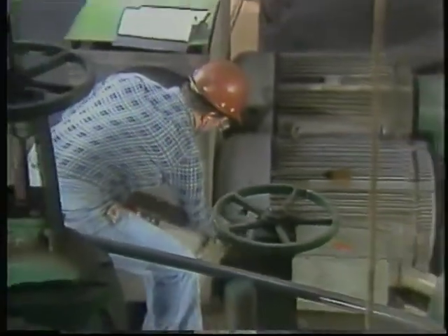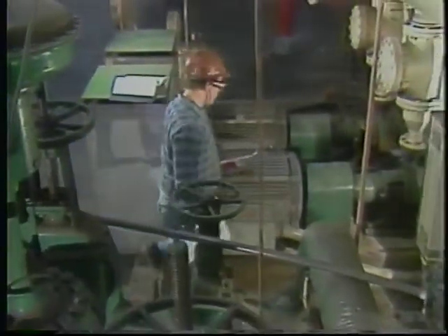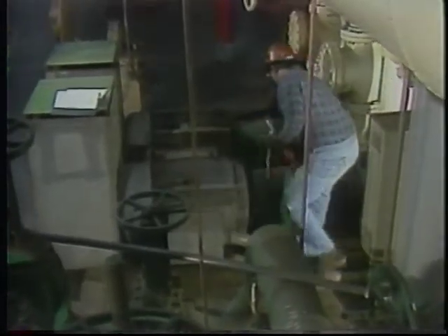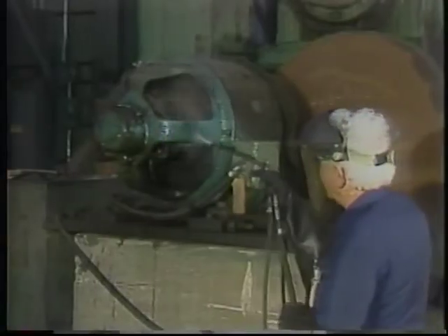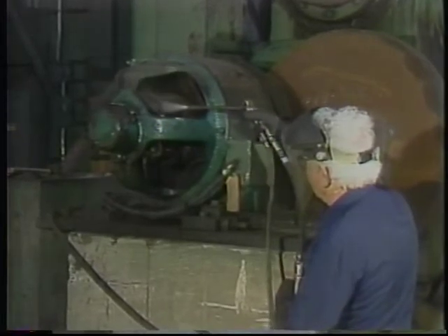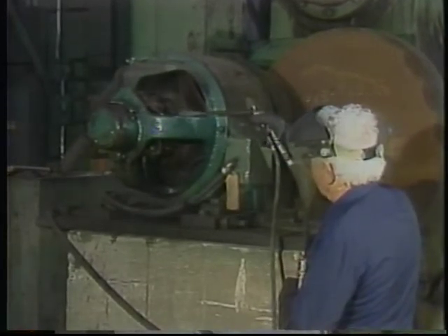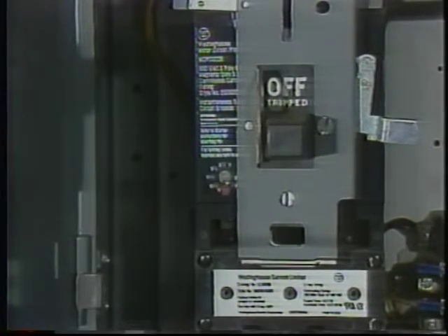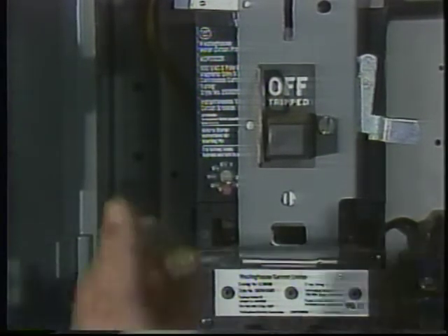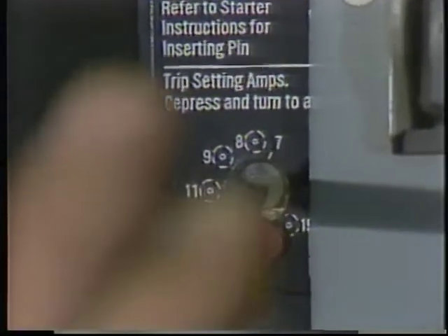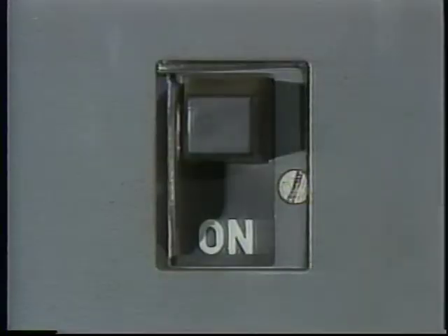In practice, much of motor maintenance involves keeping friction low in motors and associated equipment. High friction increases the load on a motor and makes it more likely to overheat and burn out. Maintenance also should ensure that a motor can get rid of any heat that it does produce. Installing and connecting a motor requires careful attention to the setting of the overload breakers. They monitor the current to the motor and trip open when current is more than rated full load current for too long. Their purpose is to prevent a motor from burning out under overload conditions.